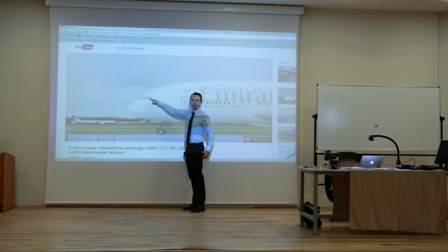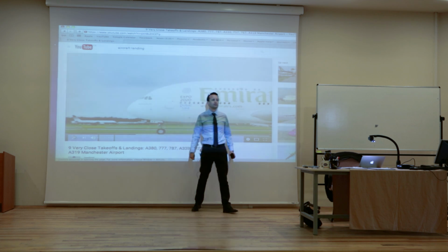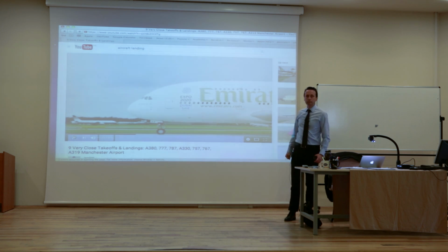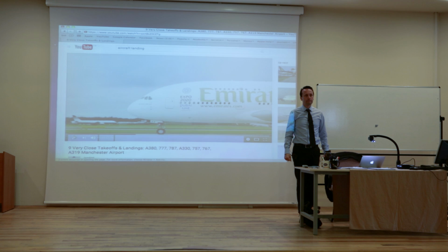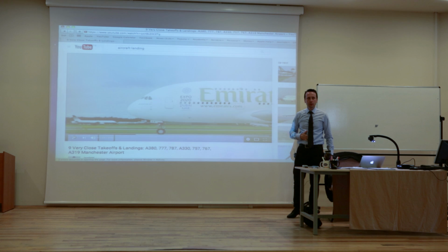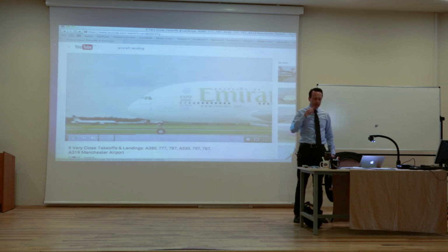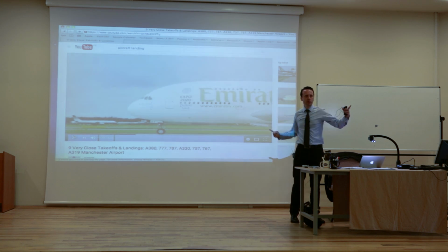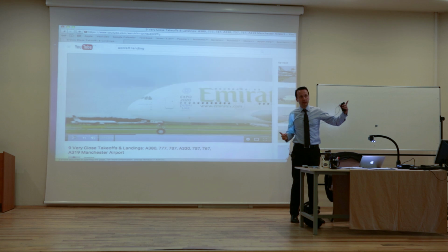Do you see my Pitot tubes? Why do you use Pitot tubes on the nose of the aircraft, but not near the beams? Because the flow could change due to disturbance of the aircraft. So why do we use them in front, not on the wings? Because we are interested in the real velocity of the air. See, if you put them on the wings, there's no problem. But when the airplane starts doing this, one Pitot tube will measure more than the other one. So you are also measuring that rotation.